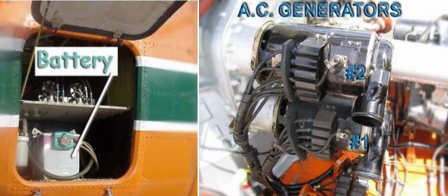AC power supply system. The alternating current system power is supplied by two brushless alternating current generators. A DC operated inverter and an AC powered external receptacle provide secondary sources of AC power. The AC system consists of the following components: generators, generator switches, current transformers, current limiters, auto transformers, ground inverters, inverter power relay, inverter transfer relay, inverter control relays, under frequency microswitch, supervisory and voltage regulator panels.